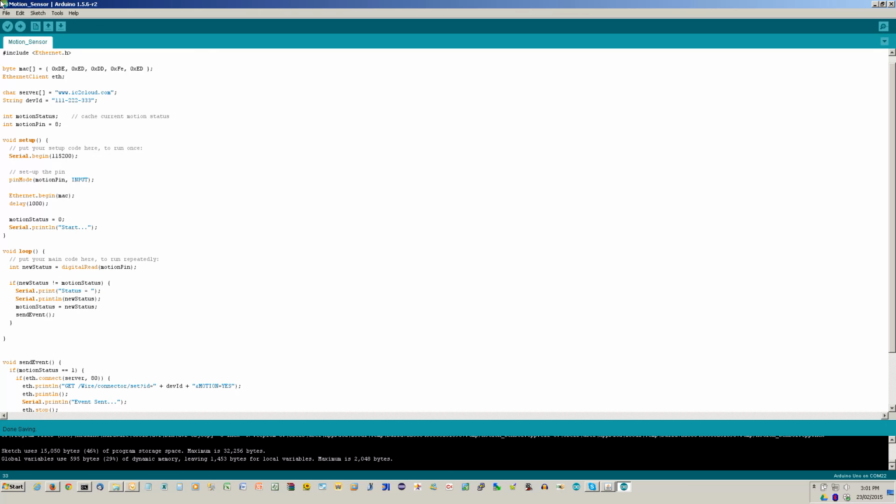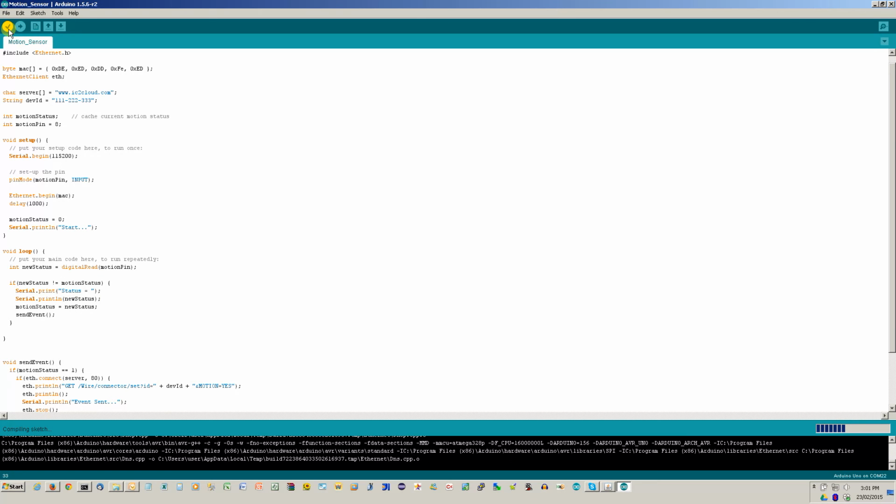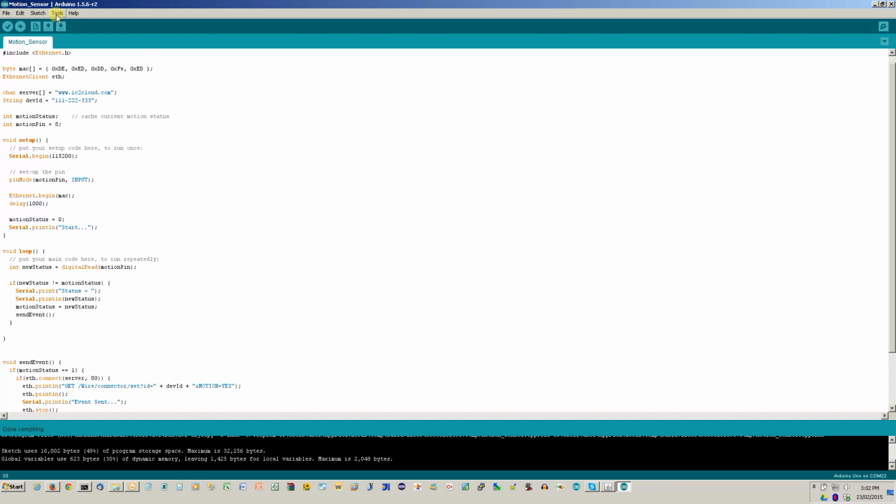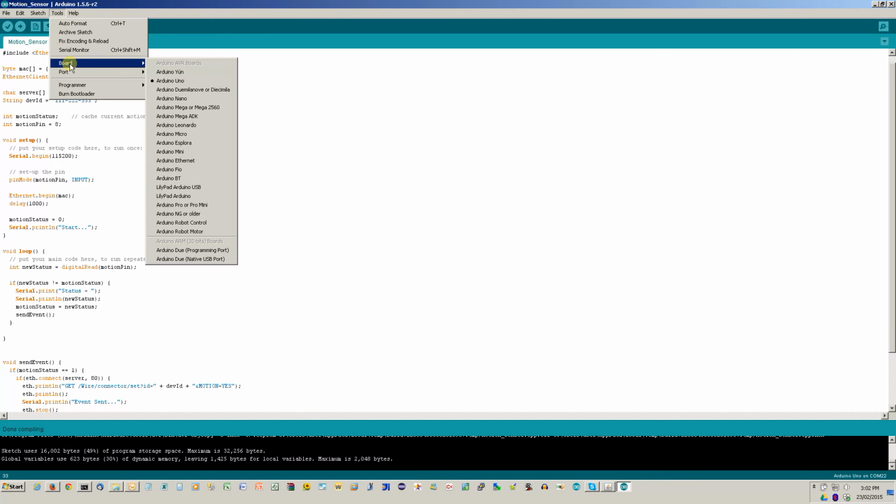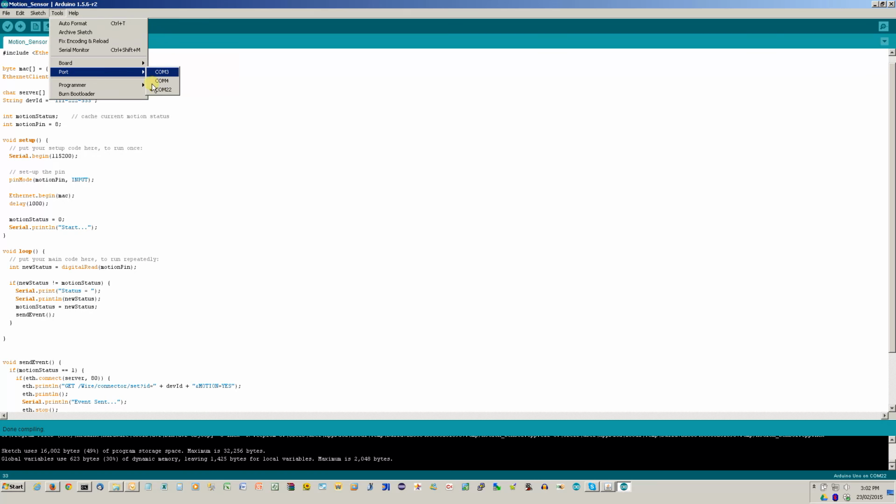You can find instructions on the Arduino website how to set up your environment, compile and upload. You need to make sure your IDE is properly set to use Arduino Uno as a target, and proper serial port for communication with the Arduino board. Once again, instructions how to do these can be found on the Arduino documentation.